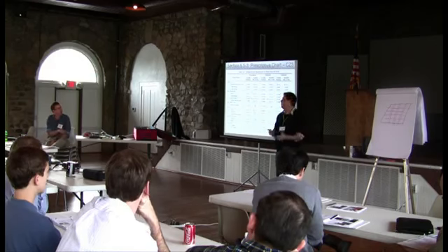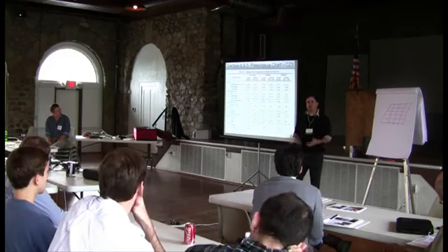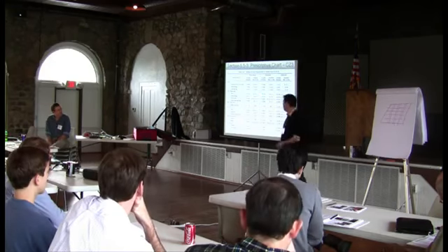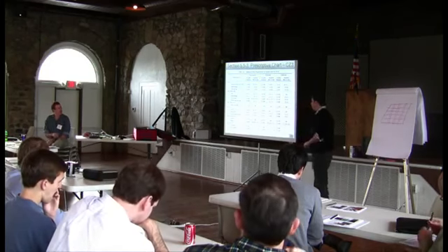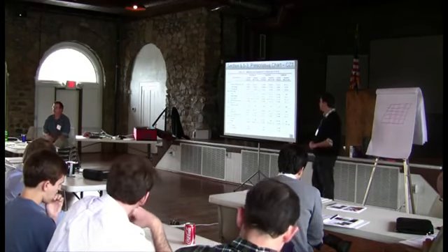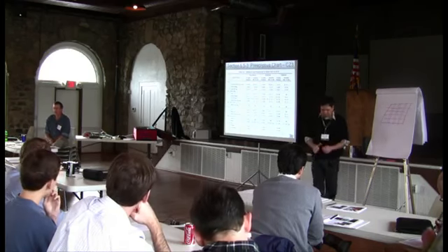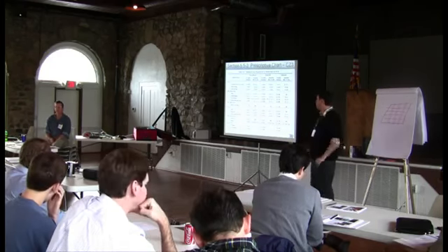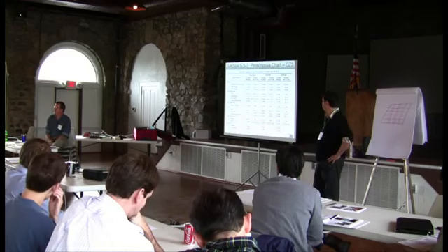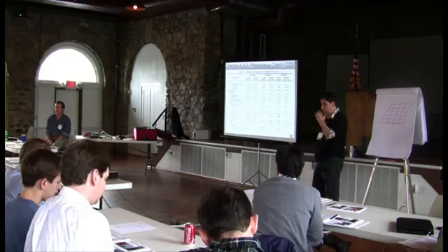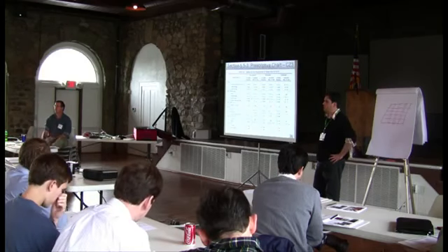Not a slab on grade, but maybe you have a crawl space, or maybe it's over a parking deck or something like that. You are going to have to insulate it based upon these values. Since slabs are very prevalent in commercial buildings, that's the most common foundation we see in a commercial building, almost always the case. So there is no requirement for slab edge insulation in the commercial code, and not until you get into really, really cold climate zones do you have to do any insulation.